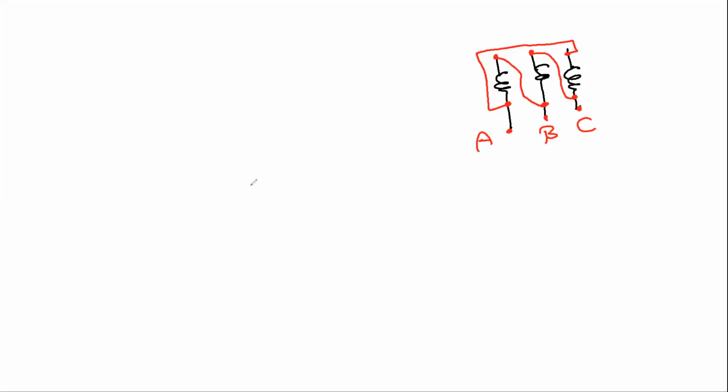We can say power equals I squared R. Is it right? But here we have to multiply by 3 because it's three phases. So what is the value of I phase? We calculated I phase is 20 and the resistance is 8.